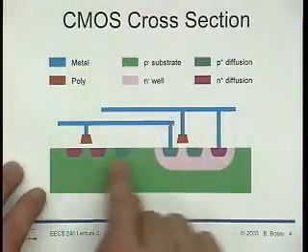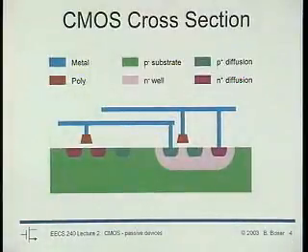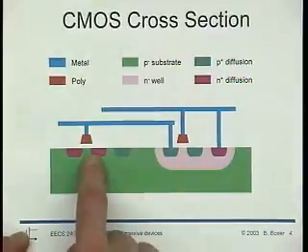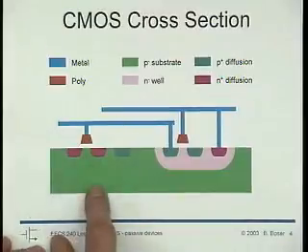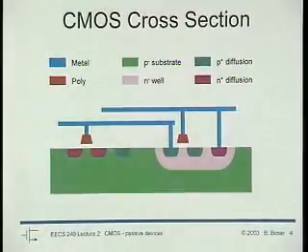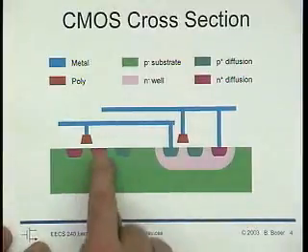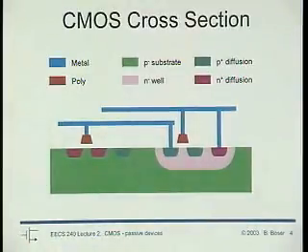Another thing is that the substrate, heck, I mean, it's a node, right? If we pull it way up, we're going to forward bias these diodes. If we pull it way down, well, then we increase the junction capacitance. And if it's unknown, then this is just a path to inject signals into the source and the drain of our transistors, where they probably add in a not very constructive way to the signals that we actually want to process.